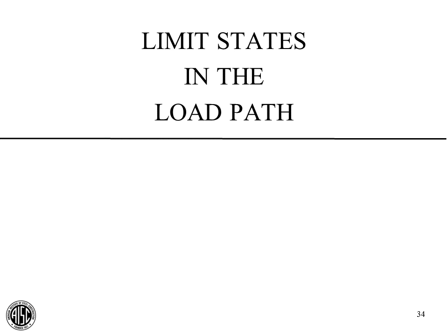Okay, so as we design connections, we need some way to identify the limit states and just to think about the design as we're going along. And the most useful way to do that, I think, is to envision the load traveling from one beam to the other through the connection. Try to visualize what limit states we would have, and then check them as we go along.